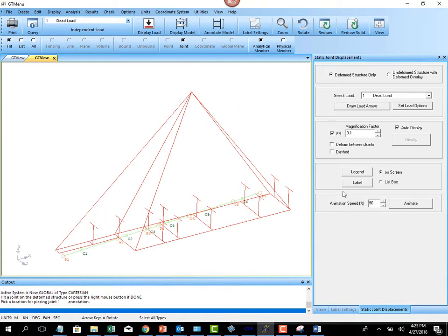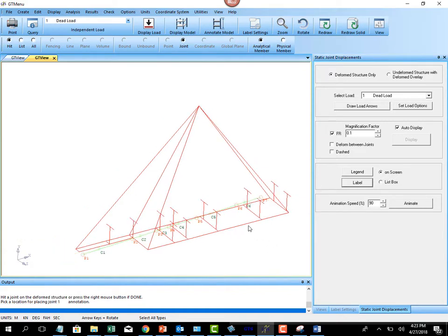Then have it displace. I mean, this is displacing about 5 meters. Okay, so it's a lot of deflection, but we can constrain that by adding some supports so that it doesn't deflect that much. Okay, but anyways, this is not analysis results because we want to do a nonlinear analysis in which the cables act as tension only members.